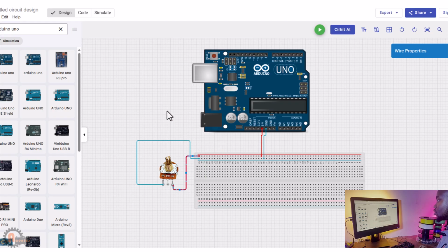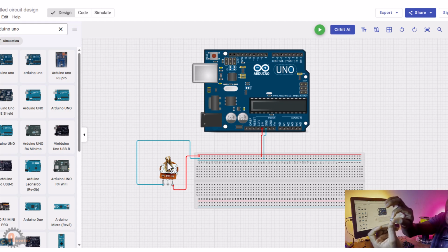That's all. So this means that if I hold the knob of the potentiometer and turn it left and right, I'm actually just sharing or balancing the voltage that's going to come out of the middle. If I turn the knob all the way anti-clockwise, I am going to be reading 0 volt at the middle pin.